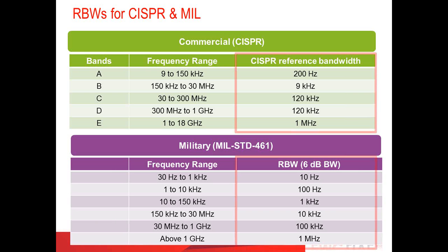One of the issues that we had was that for very slow sweep times, a dot would appear on the screen and it would slowly trace across the screen. And we tried to get creative. We had persistence displays, and you would have to adjust the knobs for each, depending on the sweep time. So that was kind of a fix, but ultimately by going digital, by sampling the signal and having trace points, trace memory, we were able to get around this issue.